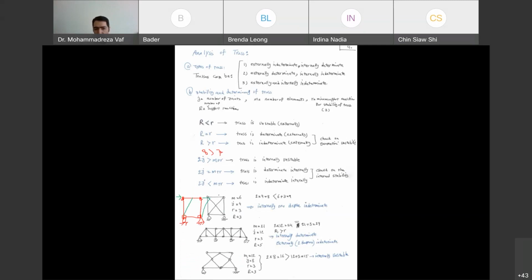However, the other truss that you can see here that has one diagonal element, the moment that you apply the force, is going to resist, because the element is going to tolerate the force that comes horizontally to the truss. So what we say about instability that leads to collapse is similar to this case. That means your truss cannot tolerate the force, and is going to show a large deflection inside structural elements. And finally, if the force is too big, it's going to collapse. So did you get what we mean by unstable?